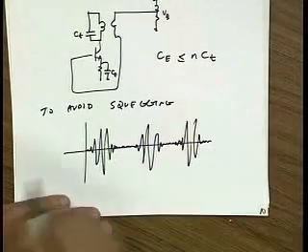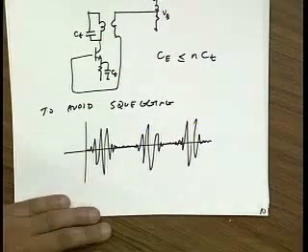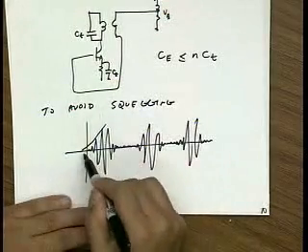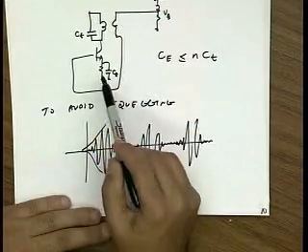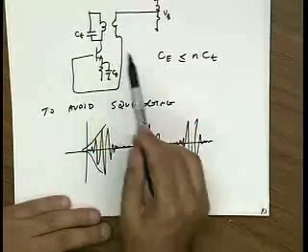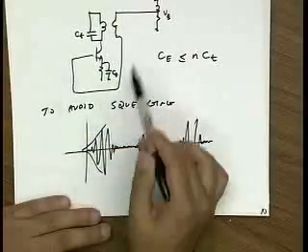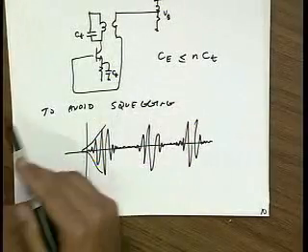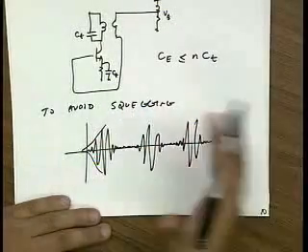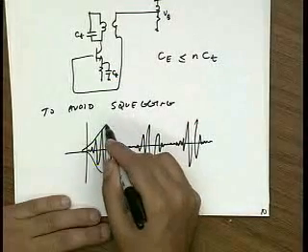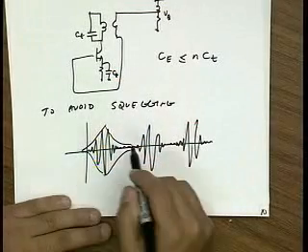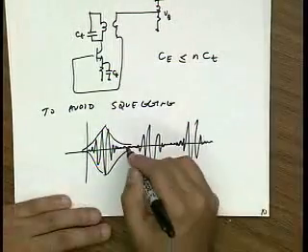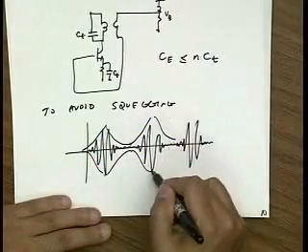And Al talked about it in his lecture. The idea is that there's some kind of oscillation going on in your bias circuit. In other words, the amplitude grows, but because of the time constant of this bias circuit, the bias circuit is slowing the circuit too much down, and it can't basically go into steady state in time. And so before it's gone into steady state, the poles move back into the left half plane, and the oscillation dies. But as soon as it dies, the gm of the transistor gets bigger again, the poles move into the right half plane, and the amplitude comes alive again. And this keeps happening over and over again.